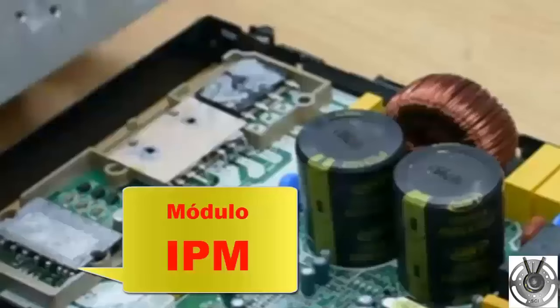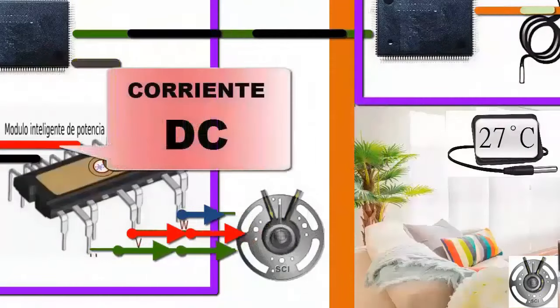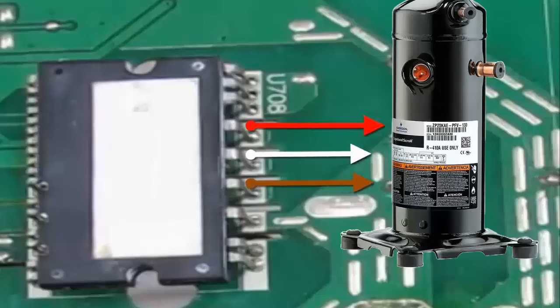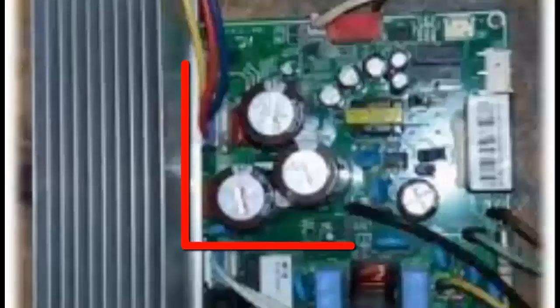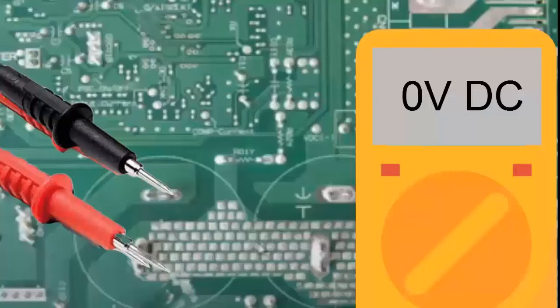H. If the IPM module has the correct voltage supply, then the problem could be with the IPM electronic module itself. Now let's look at some steps to diagnose it. 1. Disconnect the equipment from the power supply. Remember that capacitors can store current. Use a multimeter on the DC voltage scale to measure across the capacitors and ensure they are discharged.